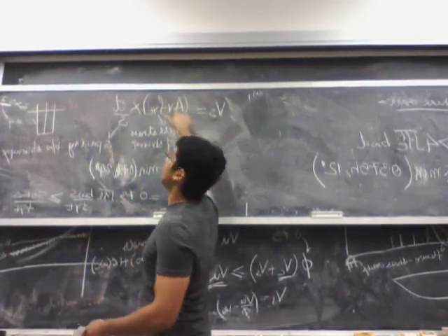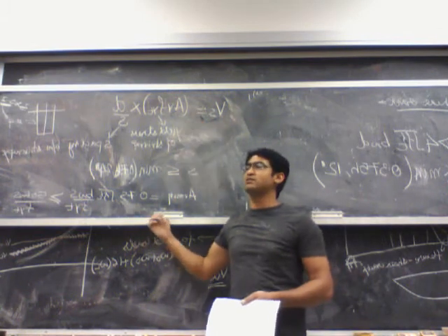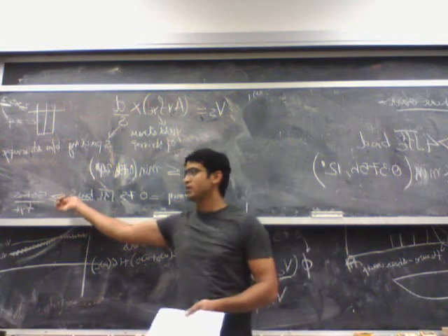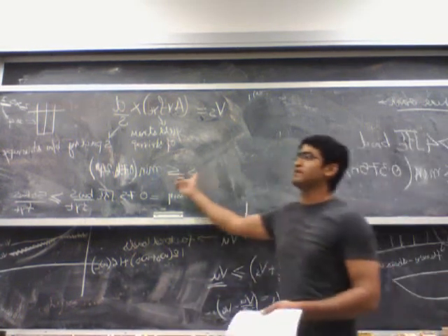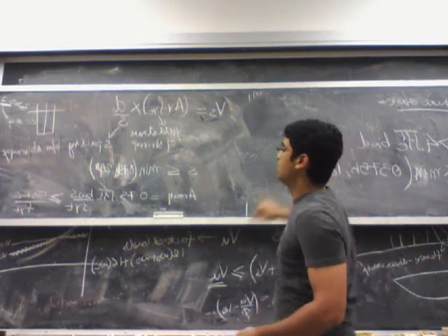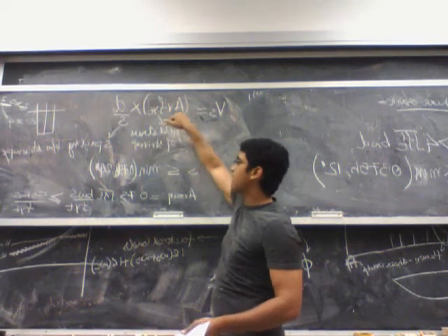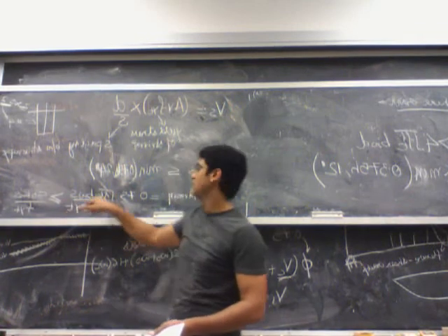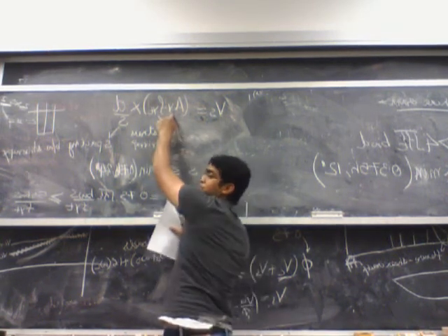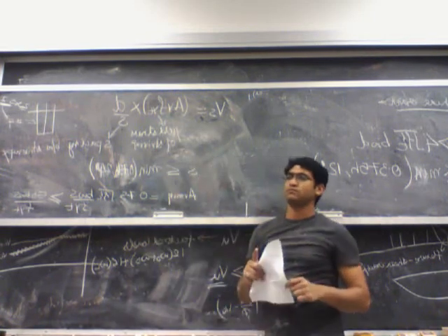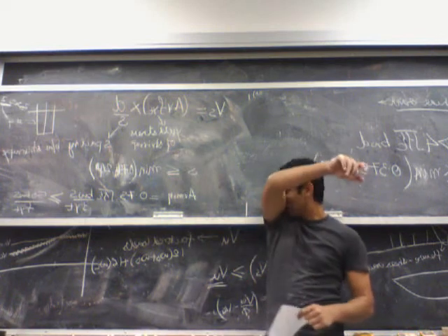Once you have the maximum spacing, you can pick the value of Av from this formula. Once you have the value of Av, you make sure that Av is greater than Av min, which again is dependent on the spacing itself. So you get Vs, find the maximum s that you can provide depending on this value. Once you have the maximum spacing, plug it here, and find Av based on this formula. Also plug the value of s in the Av min formula and pick the Av which is larger between these two. If this formula gives you a larger Av, pick this. If this gives you a larger Av, pick this. So it's a lot of checks that you have to do in a shear design. You have a limitation of Av min, you have a limitation on s and other things.